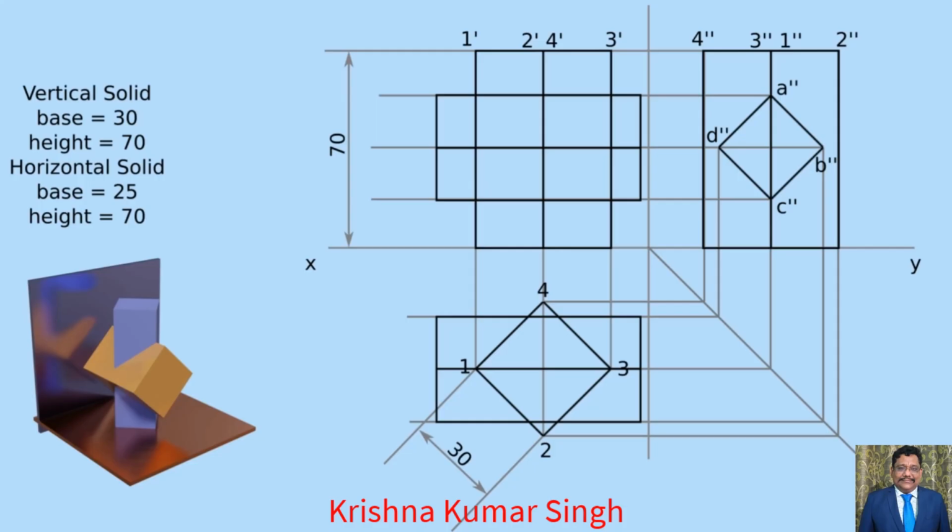Now it's time to project the intersection points. To locate the intersection points, we can see that the top views of both the prisms intersect each other at points. Now shift those intersection points upwards onto the front view using construction lines. These lines will intersect the front view at their respective edges. We will obtain intersection points on the front view of both the prisms. Give lettering to those points. These points are only vertices.